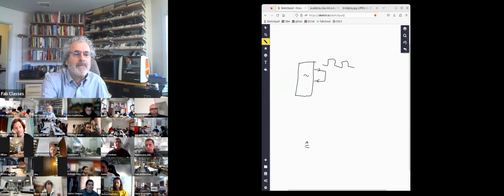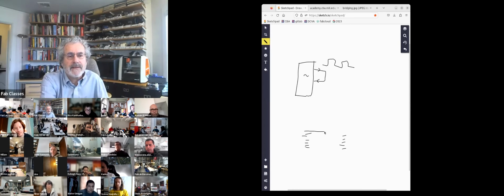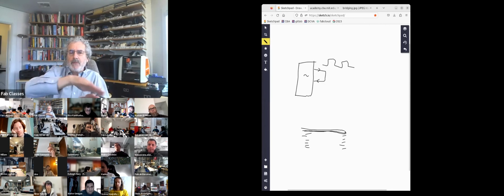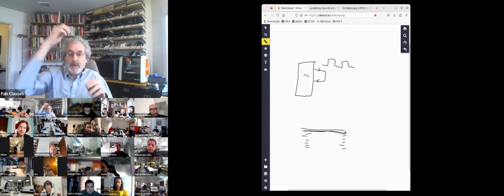if I'm building up a layer here, and I'm building up a layer here, if I then start going off into space, if I stop, I lose, I get a mess. But if I can come over to here, I'm pulling the filament from here to here, and then I anchor it here. So that's called bridging. Bridging is where you pull between two places you've built up.